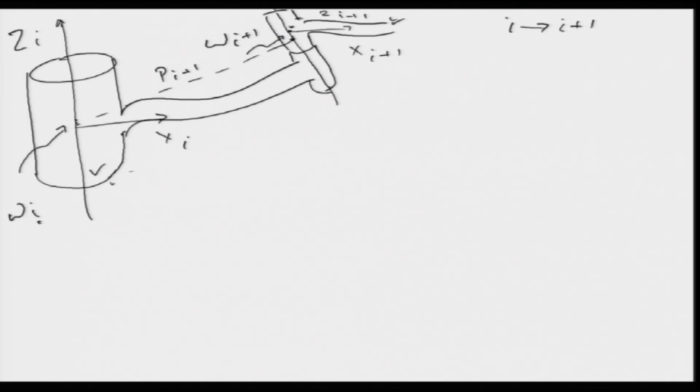So, essentially link i plus 1 will have 2 velocity components, it will have omega i plus it will have omega i plus 1. I will just write down the complete, this is just to understand, and the linear velocities are also going to move. So, now what we are saying is that because of this omega i here, this omega i will have an effect on the next link also, plus the link i plus 1 will have its own velocity, which is omega i plus 1. So, if you write it like this, omega i and i plus 1.